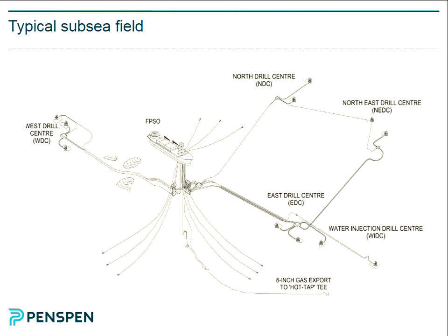And this is a dedicated manifold for water injection. With some reservoirs, reservoirs will produce naturally for a few years, and then slowly the oil pressure will reduce. And a method of actually enhancing the production from the reservoir is to inject water. So typically you inject as much water as you remove oil, or you inject more water than you remove oil, and that will maintain pressure.